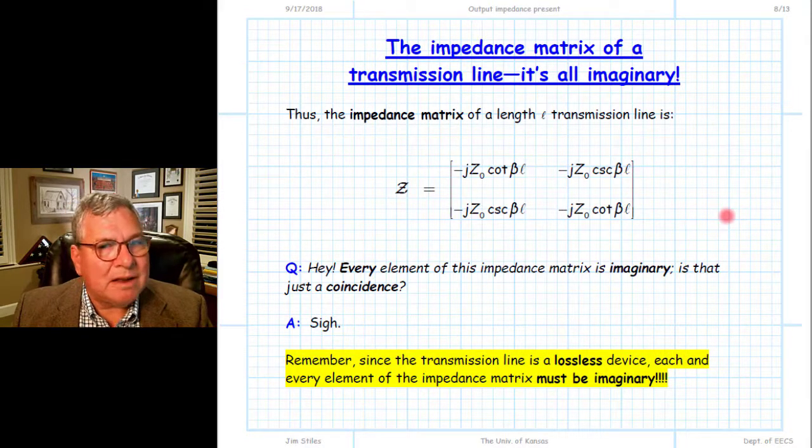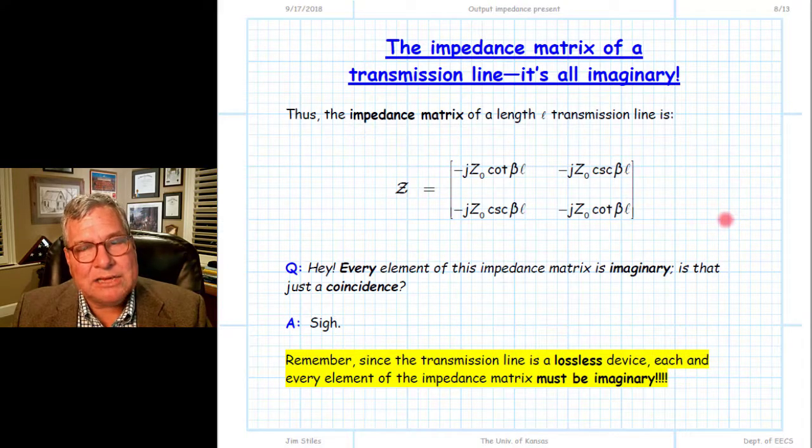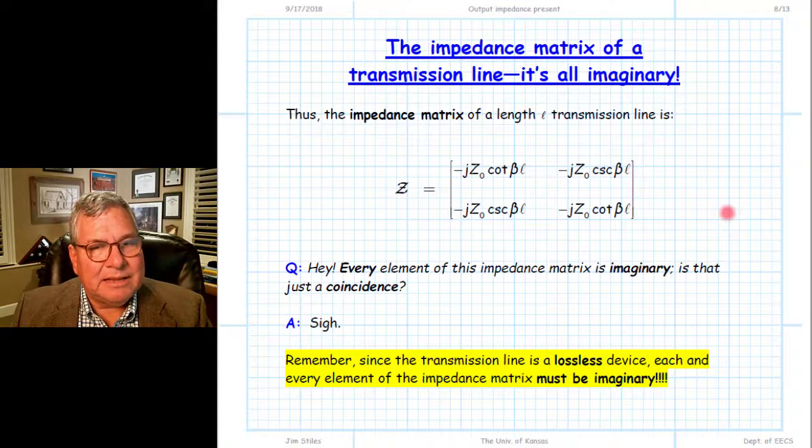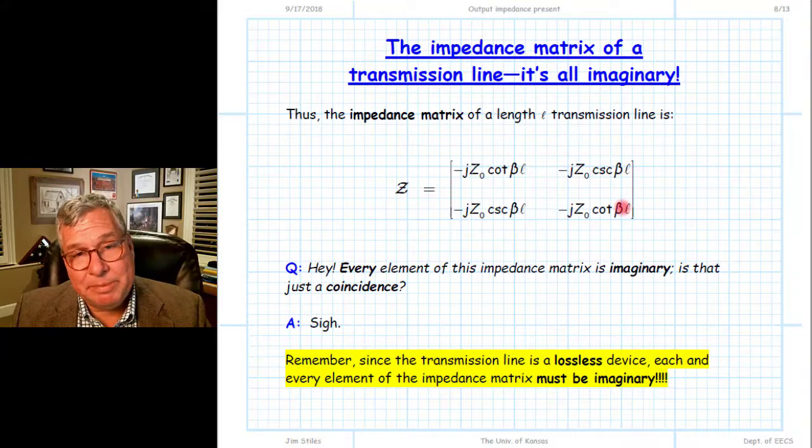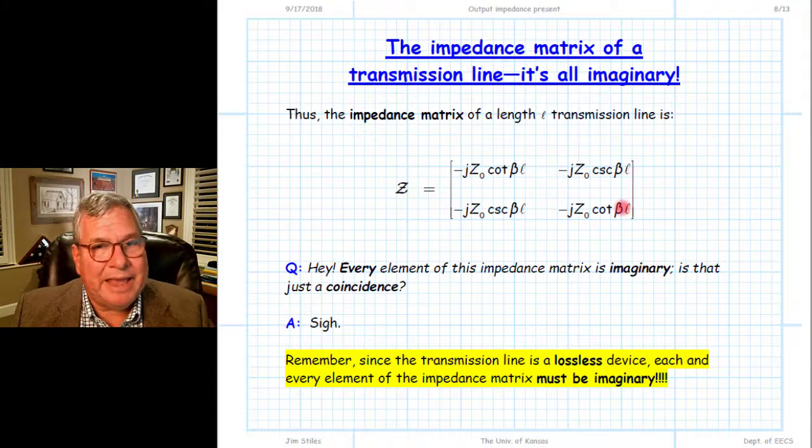Again, as I state very often, a length of transmission line has no input impedance. A length of transmission line terminating some load has an input impedance, but a two-port device does not. A two-port device has transimpedance parameters. We can determine the input impedance when we terminate the line in a load, but it depends on the load itself, so we can only describe the input impedance of a transmission line terminated with some arbitrary load ZL, and it will depend on ZL.